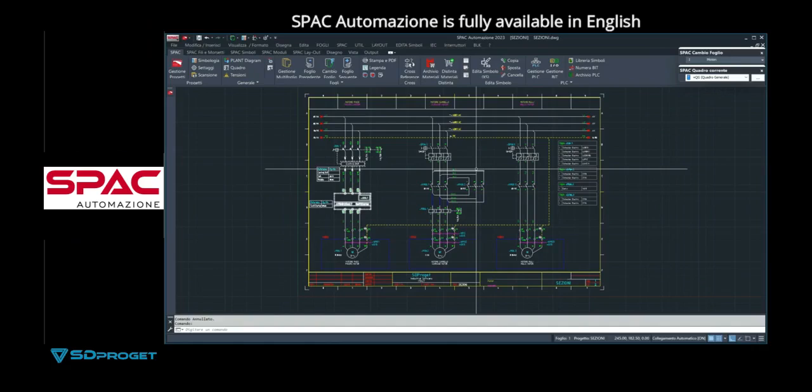because those who had never used AutoCAD certainly had some difficulty in the operation of redefining the block, and also in any case to speed up everything with 2 steps instead of maybe 5 or 6 steps for each redefinition in AutoCAD. What happened? If inside a drawing my block BLK1 was drawn as a rectangle, and I had to change it, I would open the block and make it a circle.